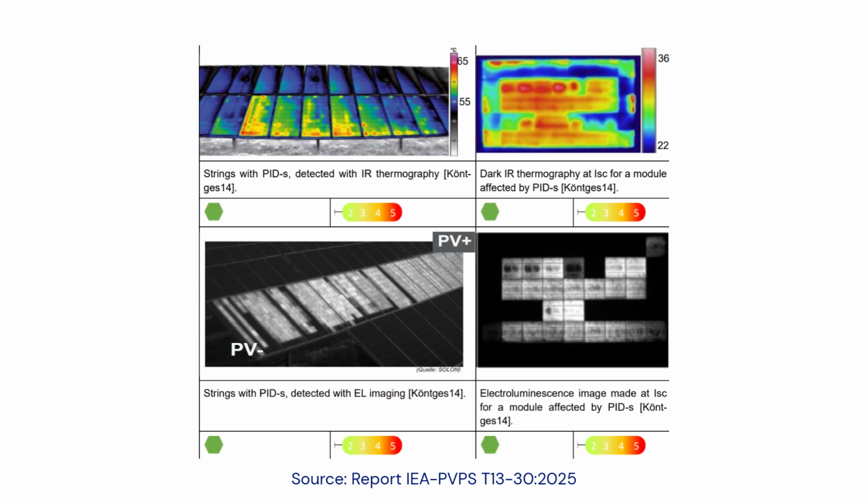Shunting degradation is induced by leakage currents coming from the displacement of sodium ions from the module's front or rear glass and through the encapsulation material. The flow of sodium ions creates shunts in the cells. For both degradation types, module and cell design has a fundamental influence on if and how much a module is affected by degradation. There are modules on the market that are designed to be degradation resistant.